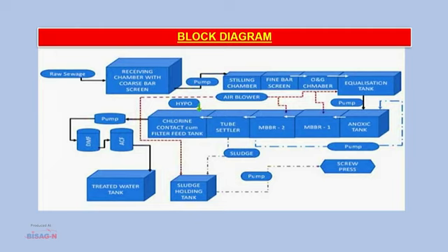Aeration is provided in the tank to avoid any settling of solids and to maintain homogeneous condition in the tank. For the purpose, a UPVC air grid having coarse holes is placed at the bottom of the tank and air from a common blower is provided. Then stage 7 is pumping. The sewage is pumped through a self-priming centrifugal monoblock pump at the average flow to the anoxic chamber.